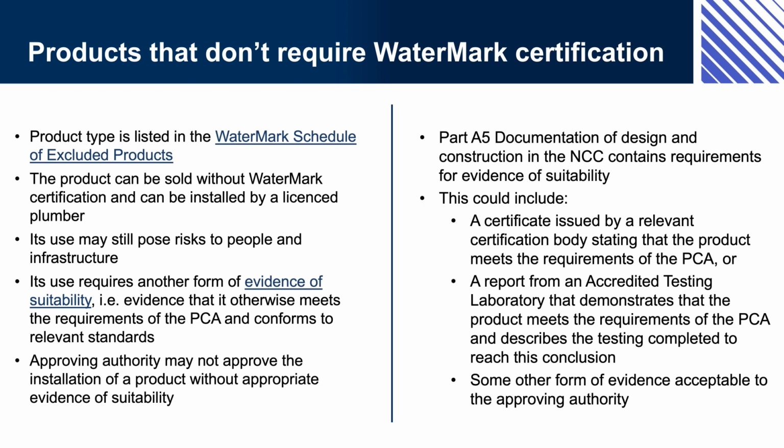Remember, some types of plumbing and drainage products don't need to have WaterMark certification. That doesn't mean that any product can be used, or that these products don't have to otherwise comply with PCA requirements or applicable Australian standards. All plumbing and drainage products must be fit for purpose, and some form of documentation will usually be necessary to demonstrate fitness for purpose. The approving authority decides what kind of documentation is acceptable in each instance.